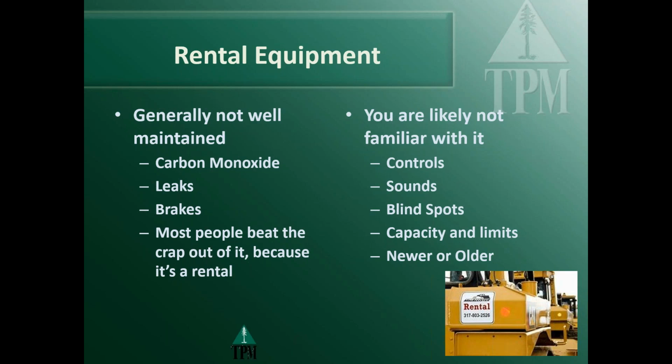But the other issue with rental equipment is that we're likely not going to be familiar with it. It's going to be a different manufacturer, so the controls will be different, different sounds, different blind spots. It's going to have a different capacity because it may be newer or older than what we're used to operating. So, give the operators some time to acclimate to it and get used to it.